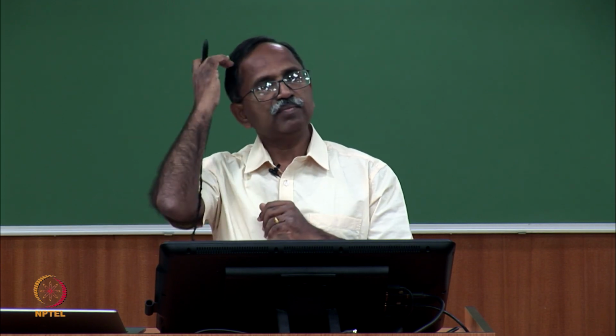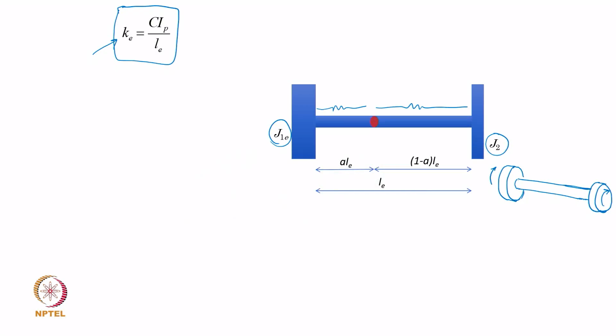because this system is very peculiar one, in the sense that as a rule we know that if there is 1 degree of freedom, there is 1 natural frequency. If there are 2 degrees of freedom, there will be 2 natural frequencies of the system. But this is a peculiar system in which the first of the 2 natural frequencies will be 0.